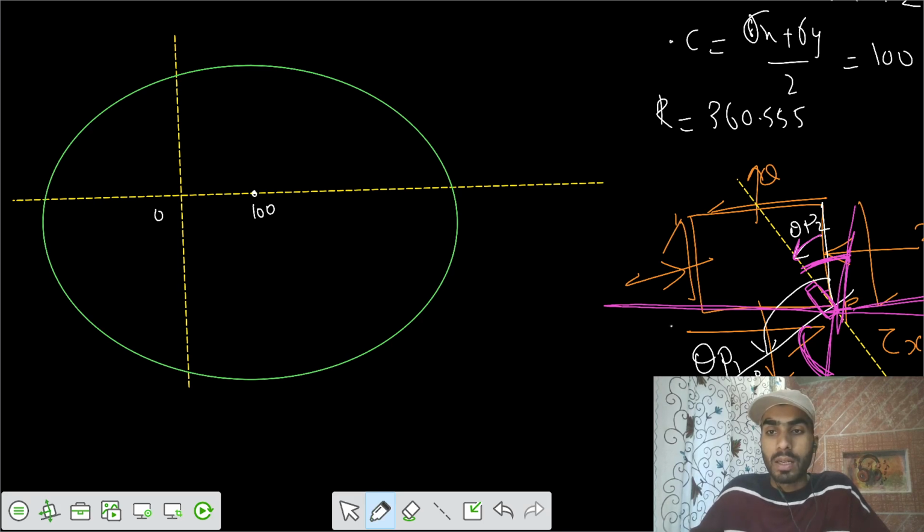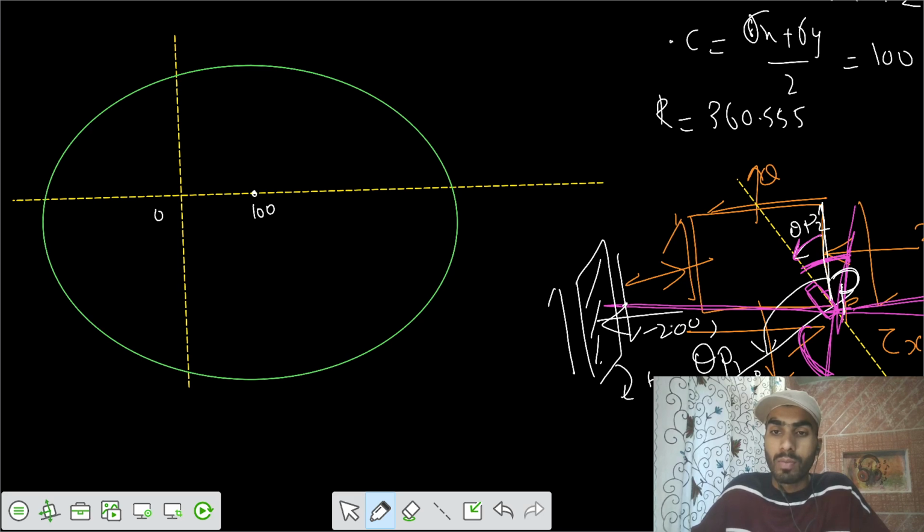Now we want to plot the P plane and Q plane. This is our P plane. On that you have compressive minus 200 megapascal and shear stress. The shear stress is in this fashion, clockwise, positive tau. So we are right. So minus 200 and positive tau. Let's say this is minus 200 comma tau. The value of the shear stress was 200 also. This point represents plane P.